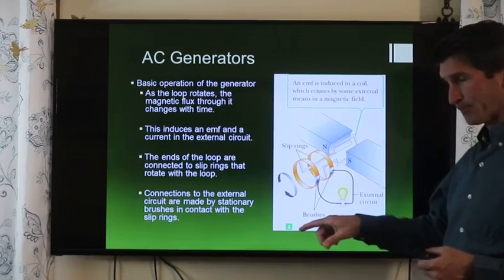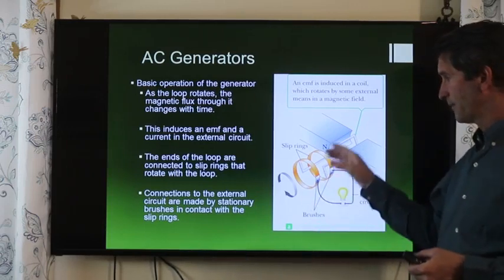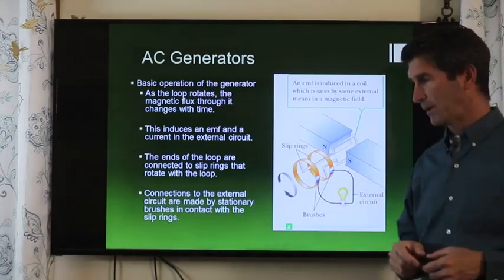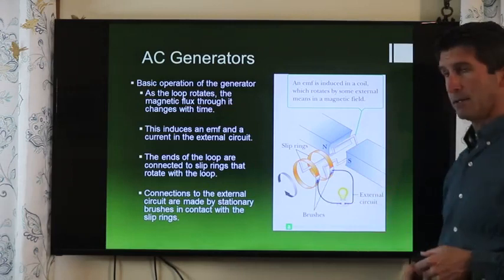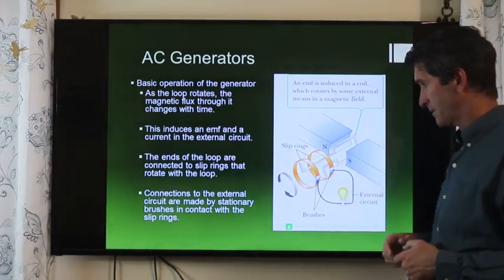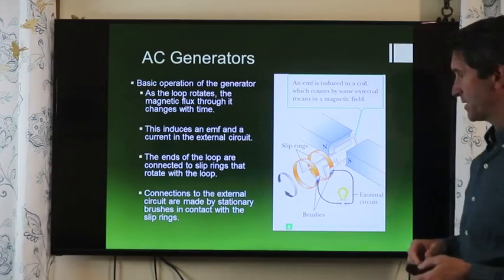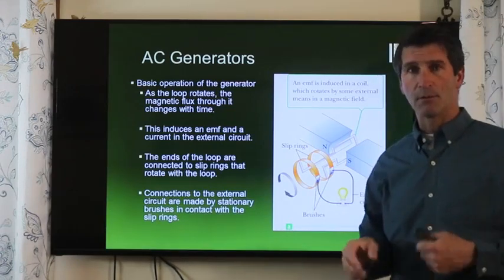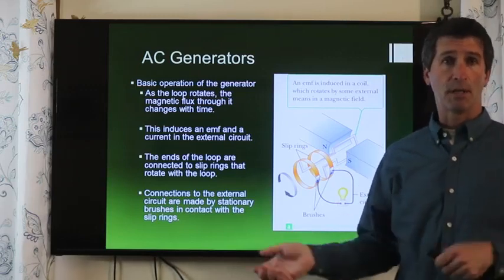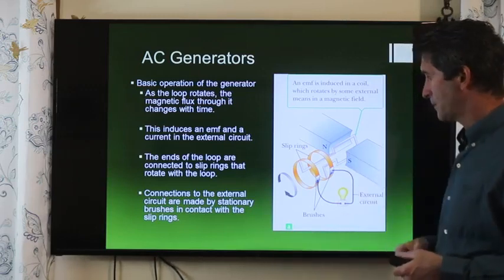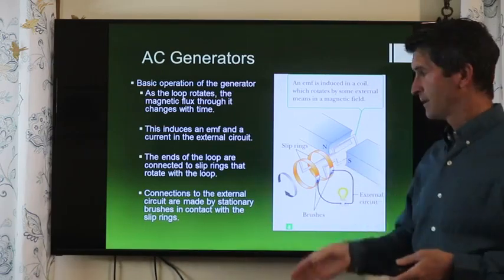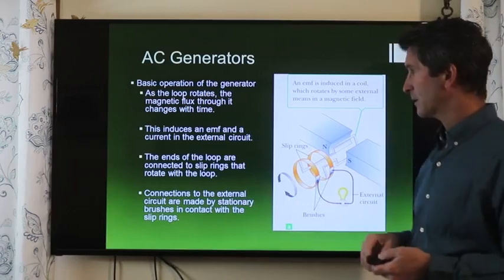If we apply an outside torque and cause this loop to move, that'll generate an electric potential here, and we can connect that to some other circuit. But again, it's AC. And if you want to reverse this and put energy into the system, your generator becomes a motor. Here you'd have to input AC electricity, and it would rotate accordingly.